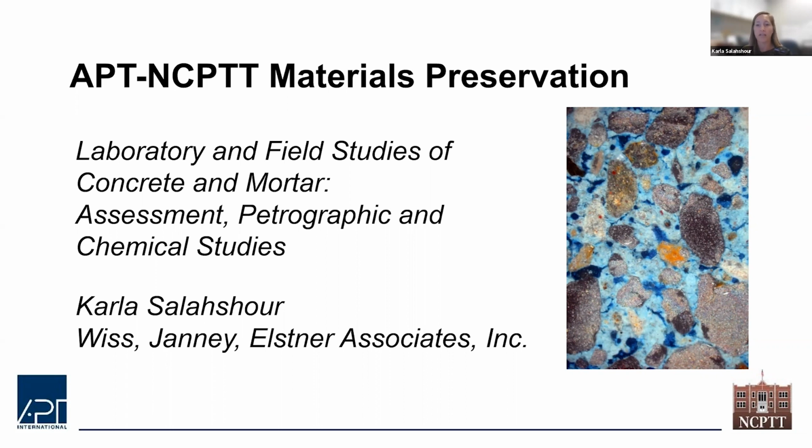So the information that we gather from the lab studies is critical to the decisions that are made regarding the approach and the treatment of historic or heritage materials. And so it's really important to understand this historic context and the significance of the material and the project when performing the testing, when we're evaluating the distress or deterioration, and designing the repairs. So today I'm going to be talking about lab and field studies of concrete and mortar, specifically field assessment techniques and laboratory testing involving petrographic and chemical studies.